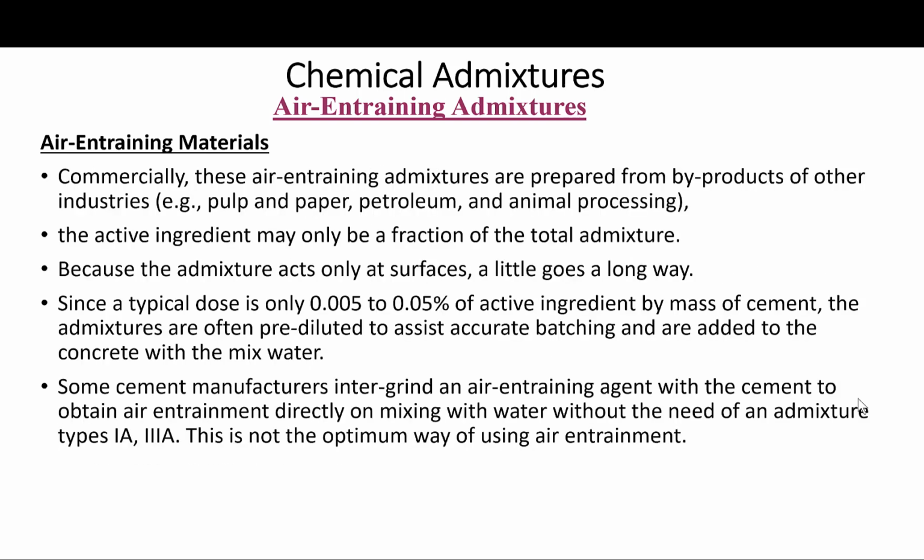Since many commercial air-entraining admixtures are prepared from byproducts of other industries, for example, pulp and paper, petroleum, and animal processing, the active ingredients may only be a fraction of the total admixture. You remember I talked about the dosing and overdosing. Because the admixture acts only at the surfaces, a little goes a long way. That's why the active ingredient is very, very small of the total